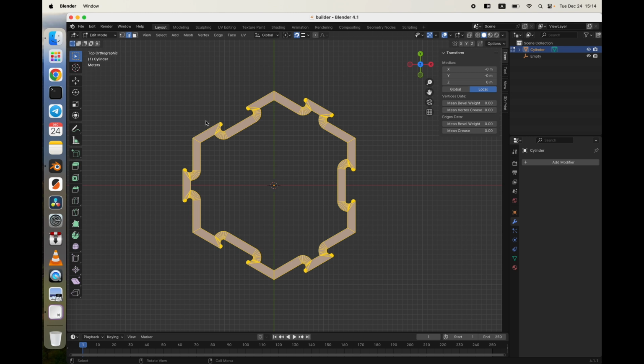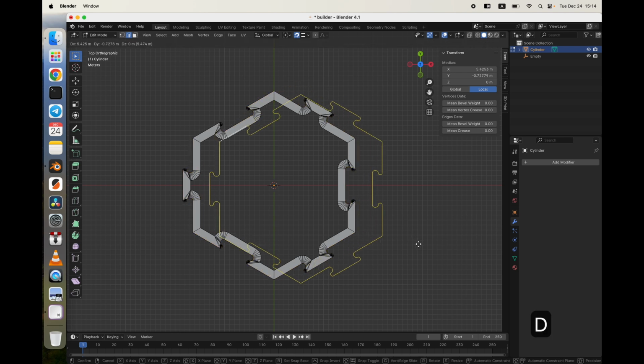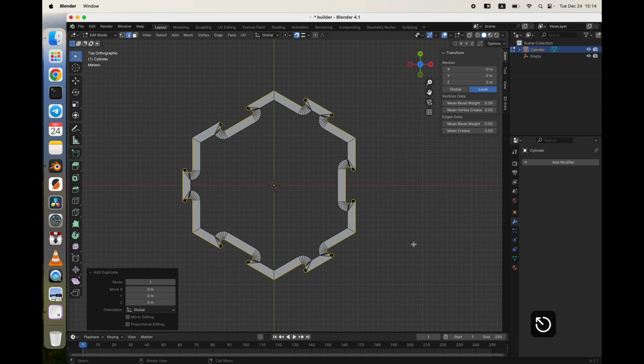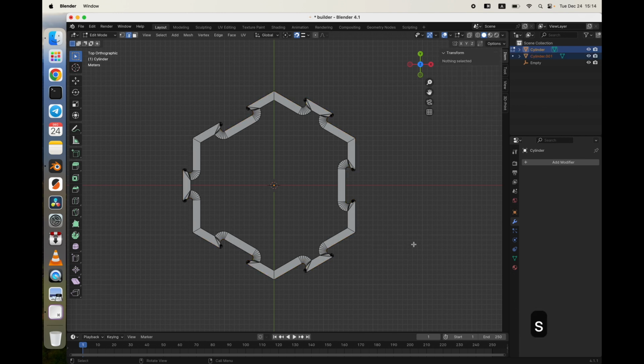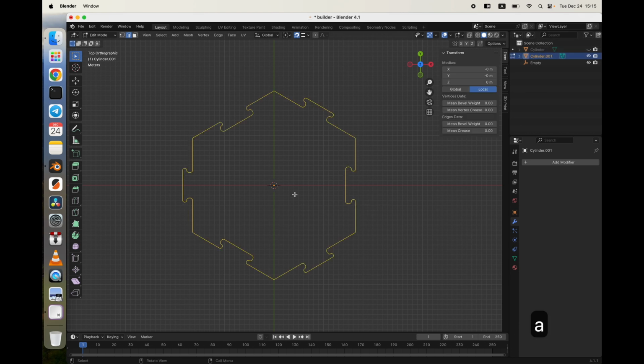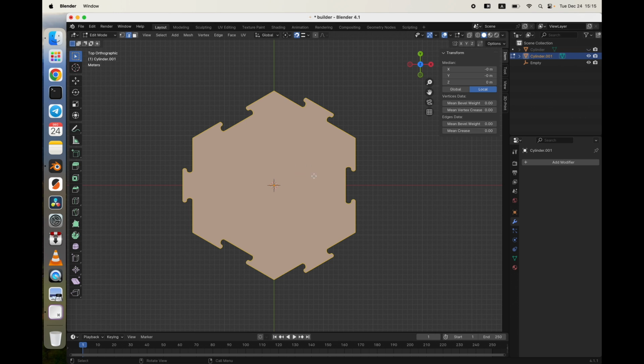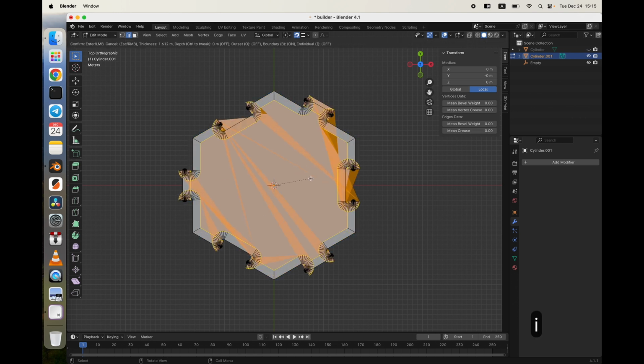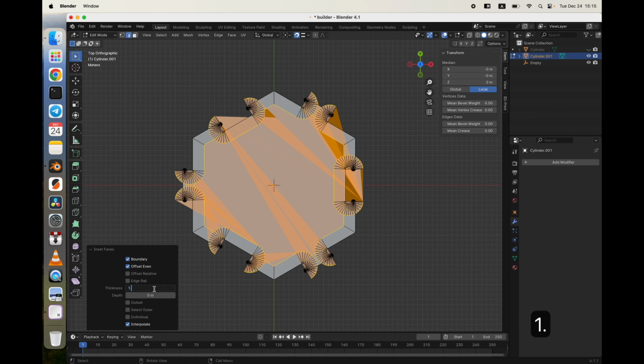And now we can select this perimeter, hold Option or Alt, click this edge, and we have selected this perimeter. Press Shift D to duplicate it, press Escape to leave it in place, then press P to separate it, and S, separate by selection. Now I will hide this mesh pressing here. I will click here to switch the edit mode to our new profile, A to select all, F to create a face, and we will inset this face, press I, and we will go with 1.7 here.